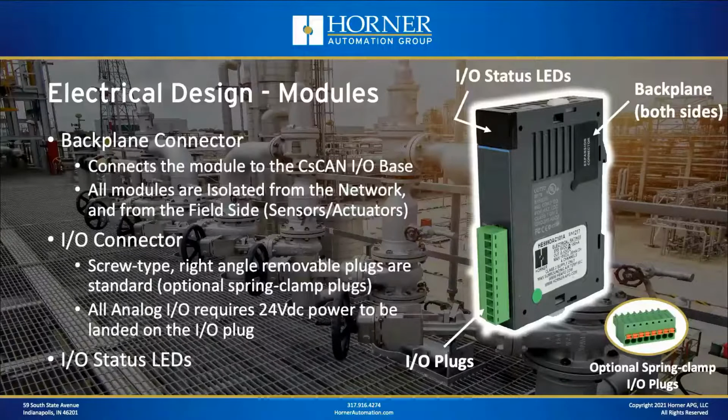Now this gives you an opportunity, if you choose to take it, to really kind of take your analog accuracy and stability up a little bit. What most customers will do, and it's okay, is that they'll take the 24 volts that they're running, let's say, to power output devices like solenoids or pilot lights or whatever the case may be, and they'll connect that and just go ahead and use that to power the analog as well.